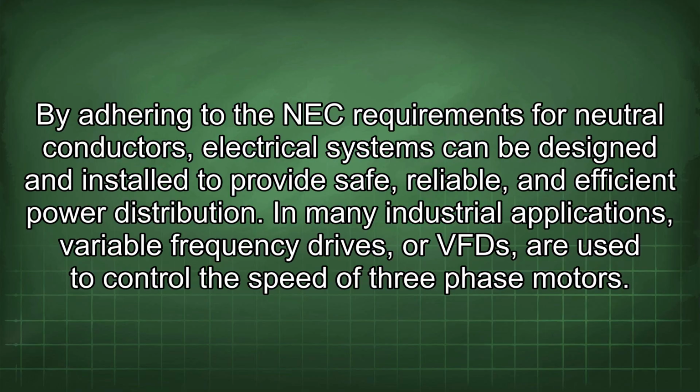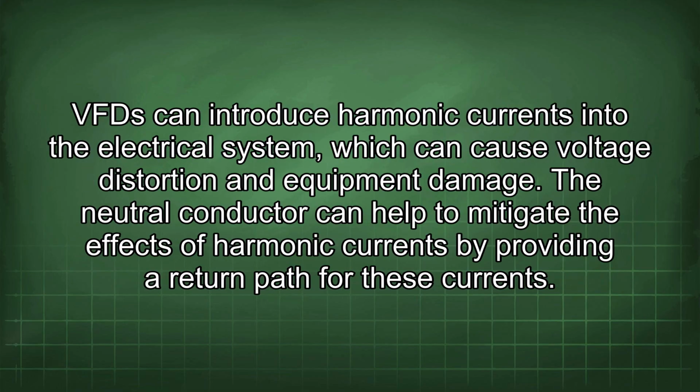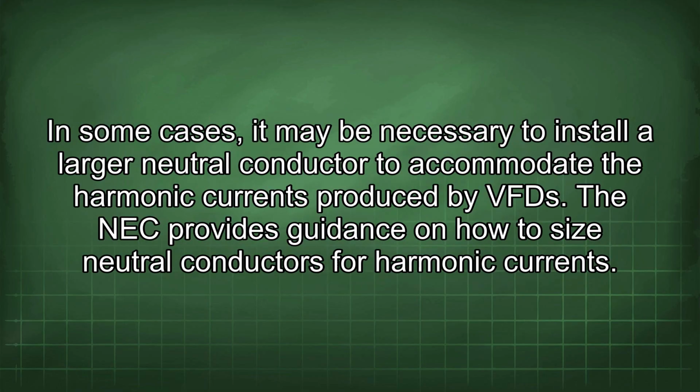and efficient power distribution. In many industrial applications, variable frequency drives, or VFDs, are used to control the speed of three-phase motors. The VFD can introduce harmonic currents into the electrical system, which can cause voltage distortion and equipment damage. The neutral conductor can help to mitigate the effects of harmonic currents by providing a return path for these currents. In some cases, it may be necessary to install a larger neutral conductor to accommodate the harmonic currents produced by the VFD. The NEC provides guidance on how to size neutral conductors for harmonic currents.